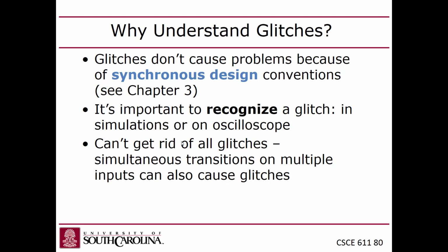So the designs look really weird because the pull-up transistors are big and the pull-down transistors are small. It looks kind of funny, but that's how you always design chips, at least in CMOS design, which is what everyone's been using for decades.